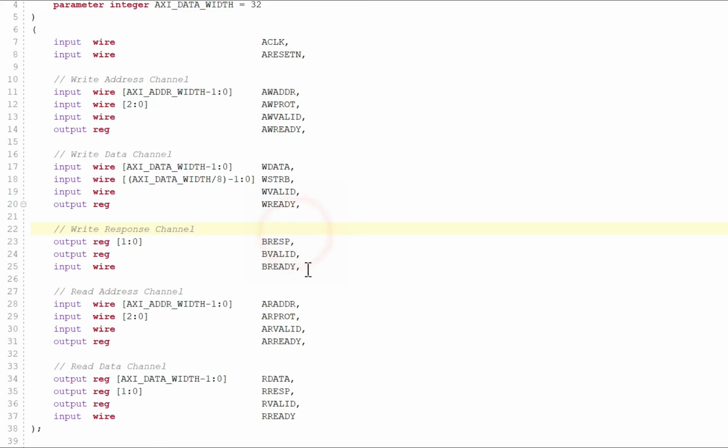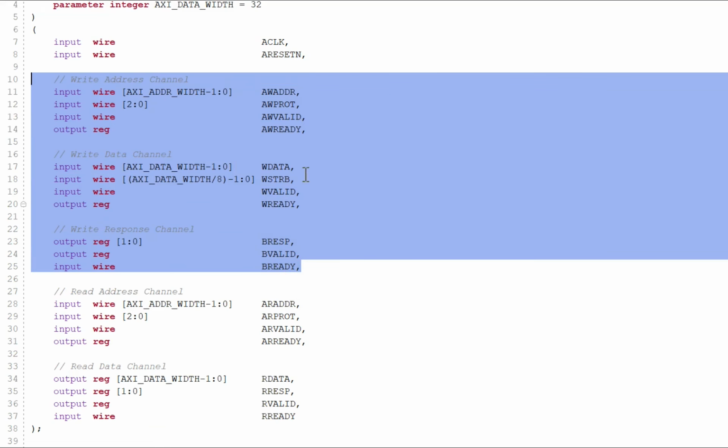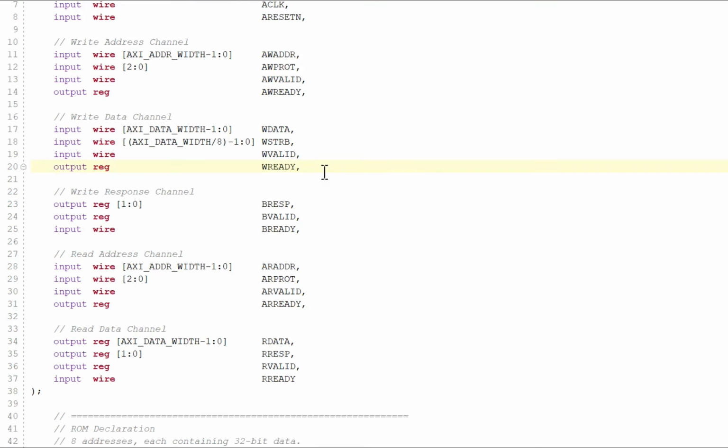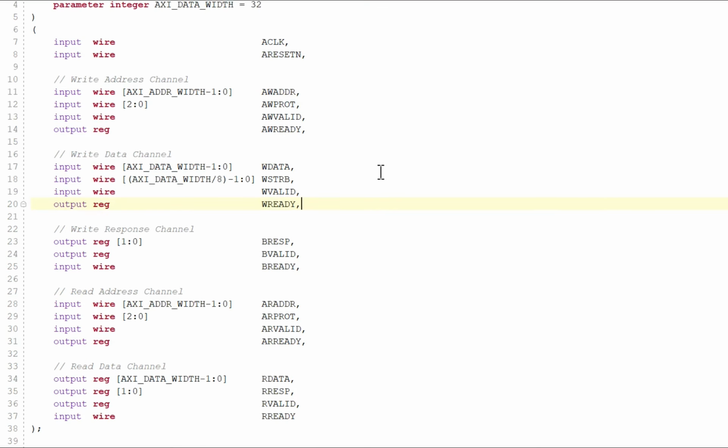This video is focused on the read bus, so the write bus is not the main topic here. However, the write bus is included so that Vivado packages the module as a complete AXI4-Lite slave interface. This allows the block to connect cleanly to the MicroBlaze AXI interconnect without strange manual connections.